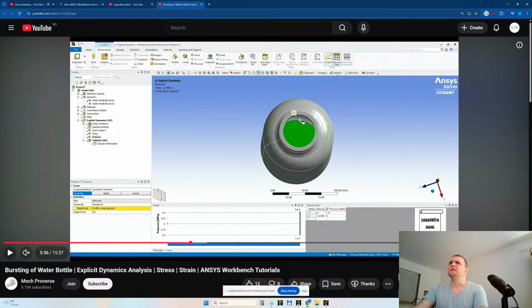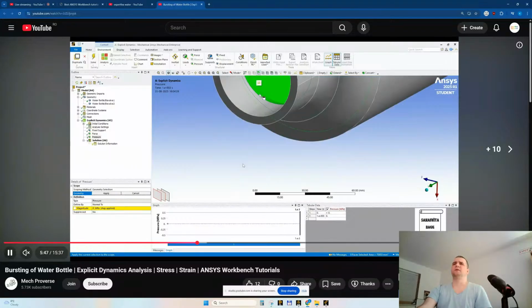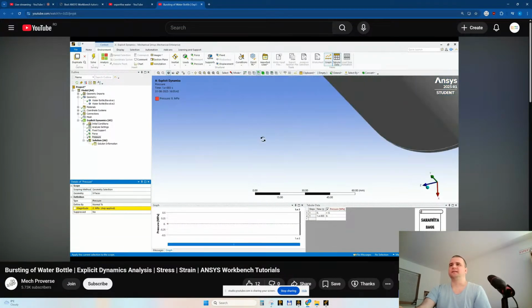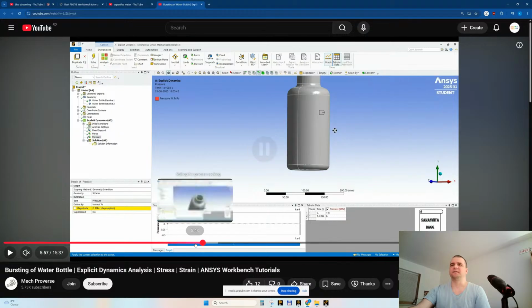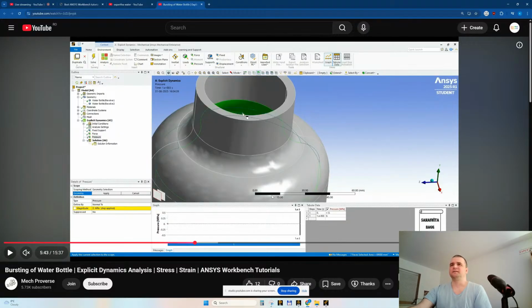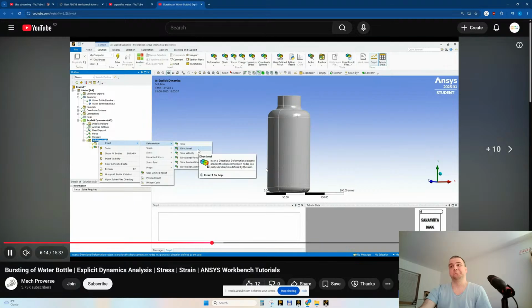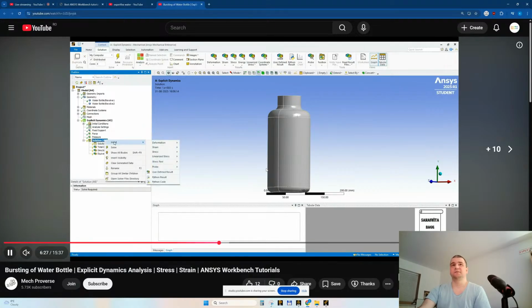You have here extend, and you select adjacent. It's right here. Sometimes it's very hard to select the faces manually, especially this face. All right, let's see the pressure, because look here. It's such a thick wall, around maybe 10 or 8 millimeters thick, and it's metal. Let's see the amount of pressure. 30 megapascals, and such a thick recipient.